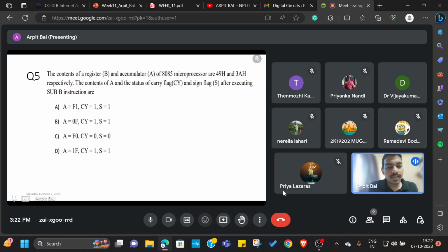The microprocessor has some status flags to let you know when there is a carry, when the accumulator is 0, what the sign is, and those things. Those are used to perform a number of functions like the jump on 0 instruction. So how will it know that the accumulator is 0? When the zero flag is set.